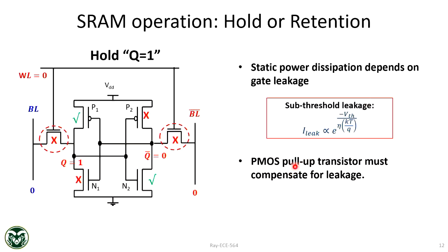So this is the leakage current, and you equate this leakage current with the on current. That's how you find out what the data retention voltage is. Make sense? There will be problems; we'll be solving concrete problems. I am giving you equations and ideas on how to approach them.